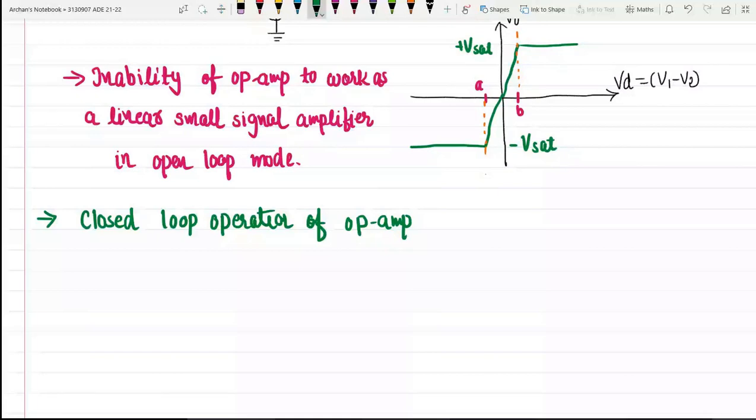Generally, in linear applications, the op amp is always used with negative feedback. This negative feedback helps in controlling the gain, which otherwise drives the op amp out of its linear range, even for a very small noise voltage at the input terminals. Negative feedback is possible by adding one simple resistor. We have already seen this configuration.